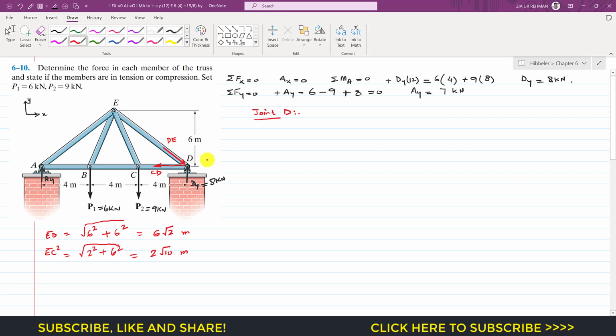So now if I apply the summation of forces along y equals 0 at joint D, first we have to resolve this DE force into its components. So it will have two components. One component will be acting like this, this is the horizontal component. It will have one component which will be acting in this direction. Let me keep these forces here. So this is the joint D free body diagram, right?